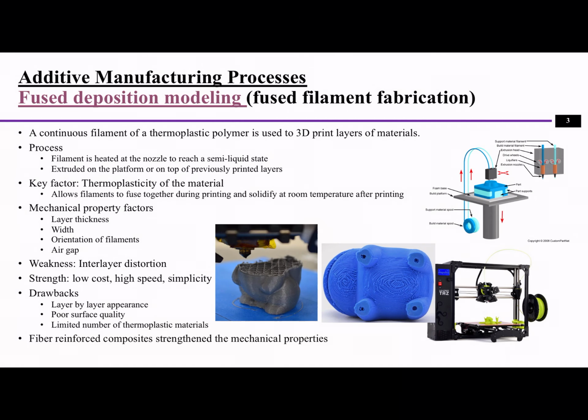All right, so that's an introduction about fused deposition modeling. When we're looking at this, we want to pay attention to the material, which is thermoplastic materials. As we talked about in ISAT430, thermoplastic material versus thermosetting elastomers, after they melt, thermoplastics can be formed into a shape again. So that's why only thermoplastic material can be used when we are using fused deposition modeling with polymers.